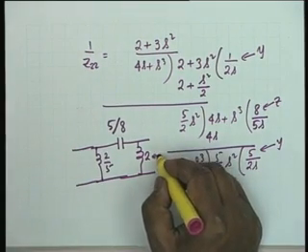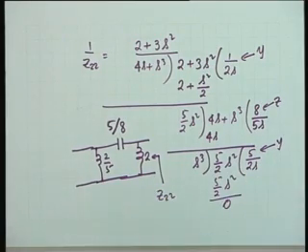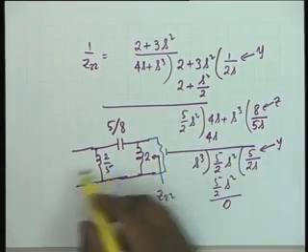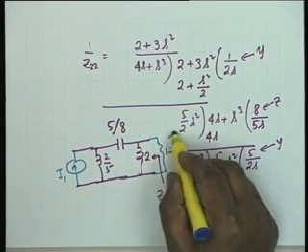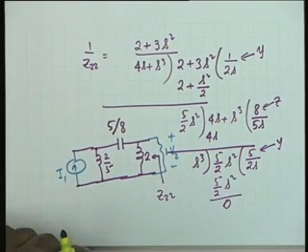This is Z22, and all that I have to do to complete the network is to add this 1 ohm resistance here and the current generator here. The network is complete. This is indeed a high pass filter. All transmission zeros are at the origin.